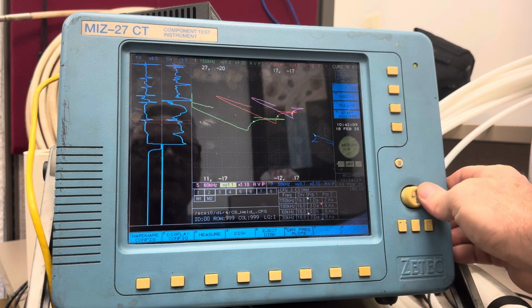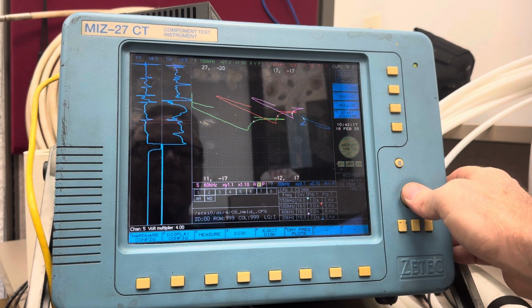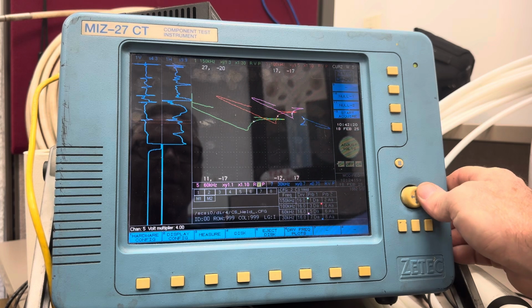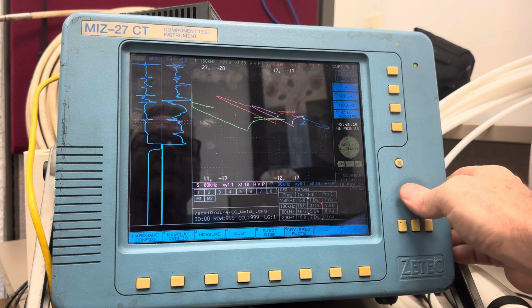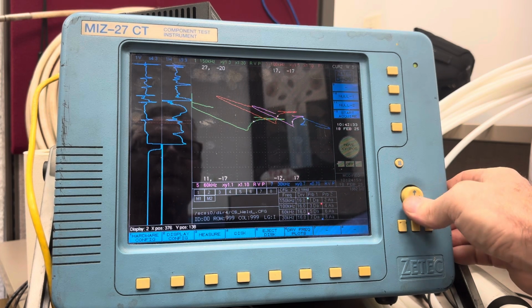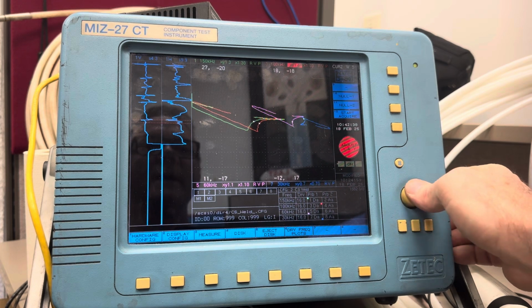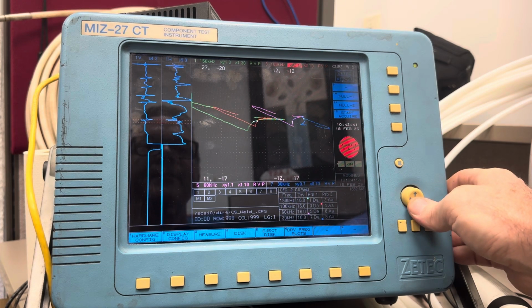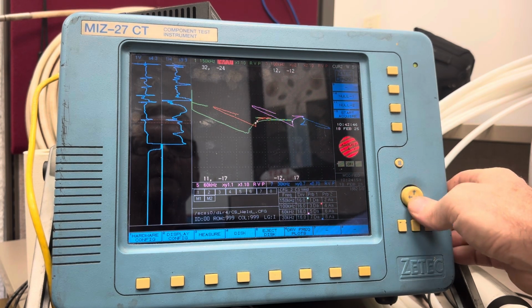But what I'm going to do is position all 4 frequencies on the same vertical position on our screen, and then we can step through the cal standard and see how they rotate with different frequencies. Put that one right about there. I think I need to crank down that span just a tad. Probably the same for 150 kilohertz. Take that down a little bit.